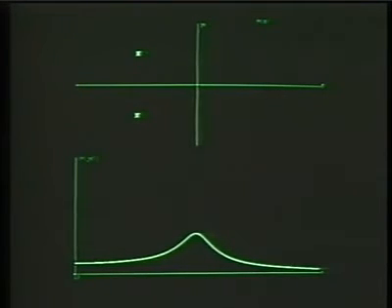And so what we see then is that for a second order system, the behavior of the resonance basically is associated with the pole locations, the frequency of the resonance associated with the vertical position of the poles, and the sharpness of the resonance associated with the real part of the poles. In other words, their position closer or further away from the j omega axis.